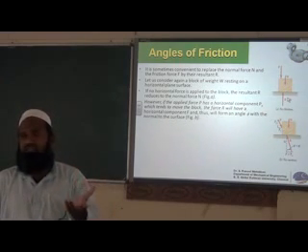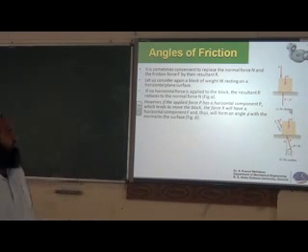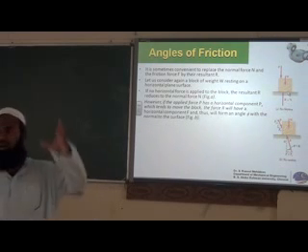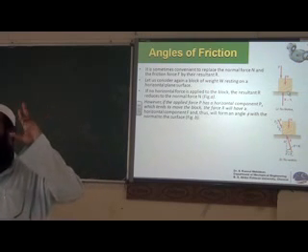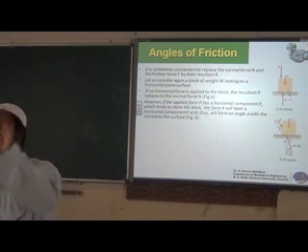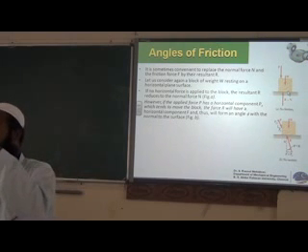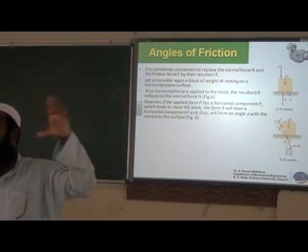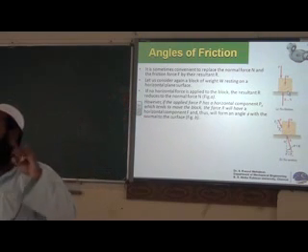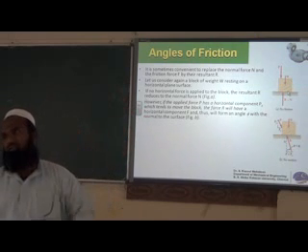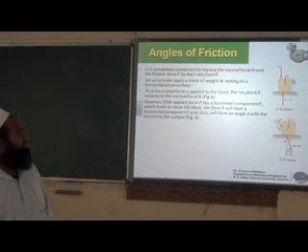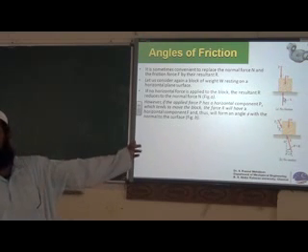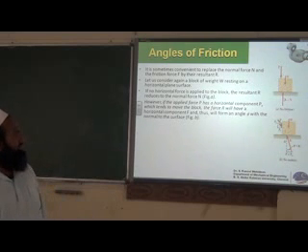For these forces, it is better to replace the two reaction forces N and F by the resultant force R. We combine the two forces and get the resultant. While showing the free body diagram, we replace the two forces, frictional force and normal reaction force, by a resultant force. In the first situation, where there is no horizontal force, your normal force will be equal to the resultant force.